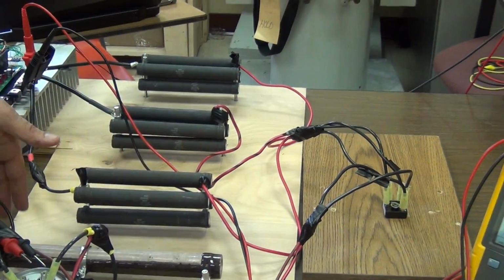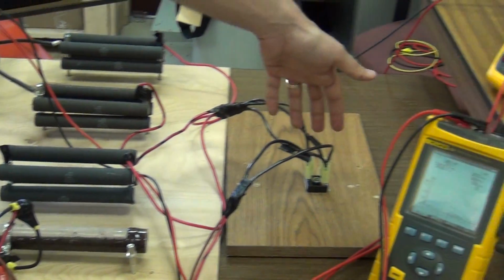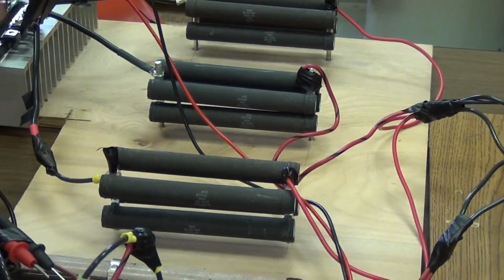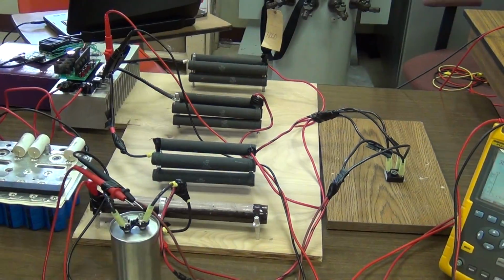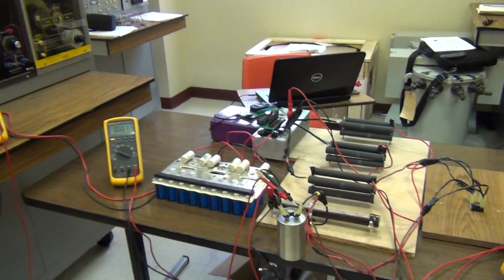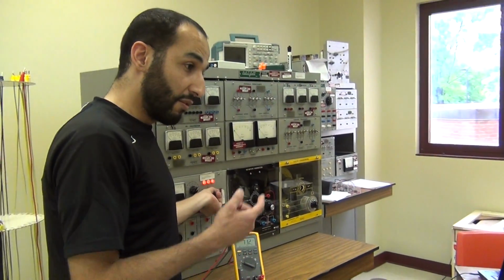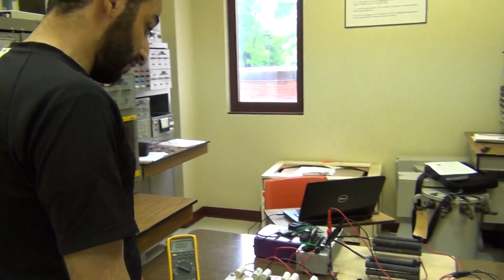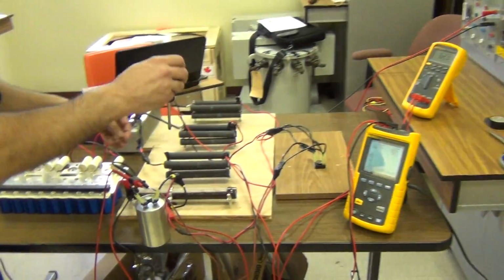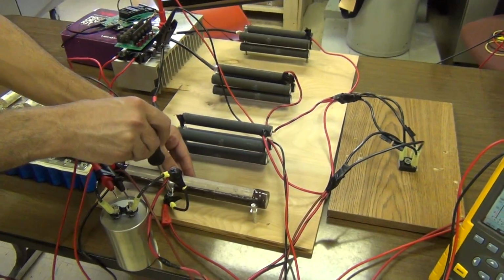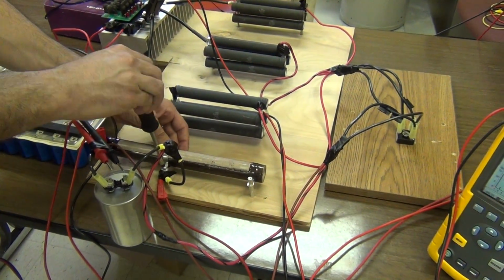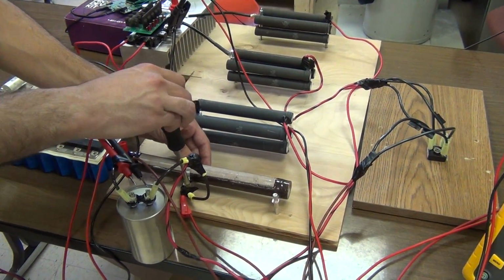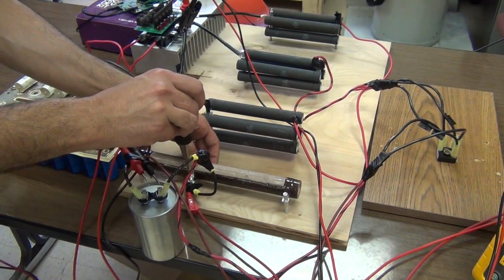Now we need to change the nonlinear load. This rectifier and this load is a nonlinear load, so we need to change that and study the effect on the total harmonic distortion. So now we need to turn off the DC power supply and change the resistance value. It should be somewhat hot, but we are working at low current, so we don't need a heat sink. Let's go to a small value.